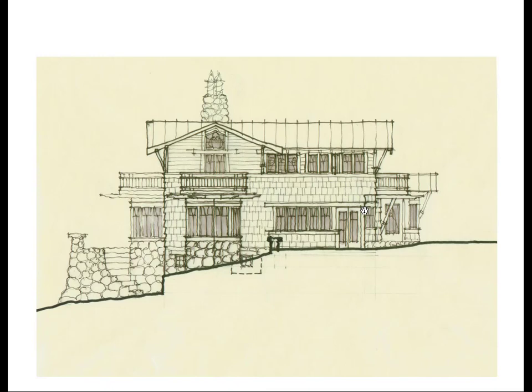So if we look at this elevation right here, what are some of the things that we notice? Based off of what we learned last class, what are some of those same techniques that you can see translated into this elevation? Anybody spot any of those? Yes. The section that's getting cut off, so the hillside, is in the thickest line. Yeah, okay. We talked about line weights, and we talked about the objects that were closer to you, or the objects that were cut. If you were cutting through it, that was typically the thickest line.